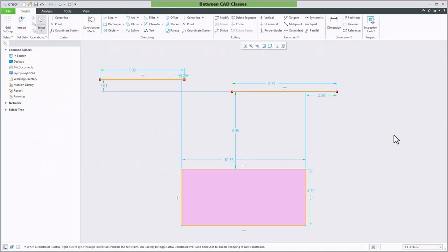In this video, we're going to take a quick look at sketching ellipses in Creo Parametric. There's two ways to create an ellipse in Creo Parametric. There is the axis ends and the center and axis ellipse. I'll begin with the default here, the axis and ends.